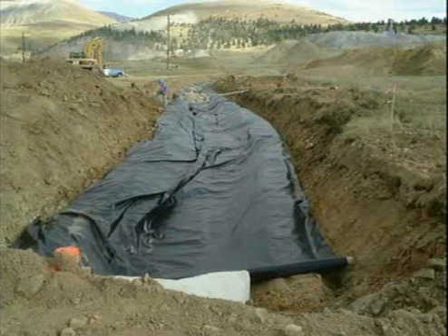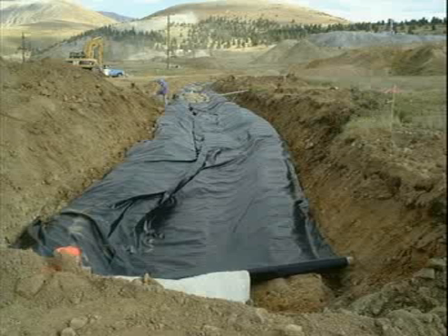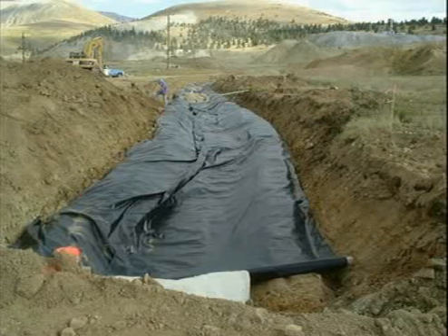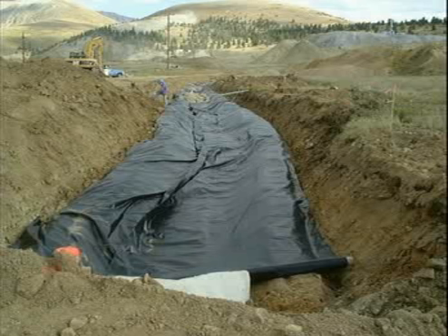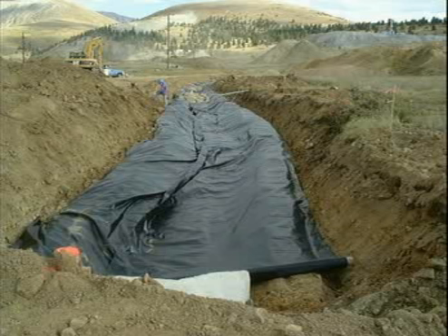This next slide here shows how the ditch liners are constructed. At the base of this particular ditch, the ditch has been dug into native material, and the native material in this case is composed of soil, but also a fair bit of rock. The synthetic membrane that lies above that rock would probably break under the load, and so this membrane is not really meant to contain all of the water. It's just meant to help convey it, because the rocks are pretty jagged. In fact, the black membrane in this diagram is actually a fine mesh.